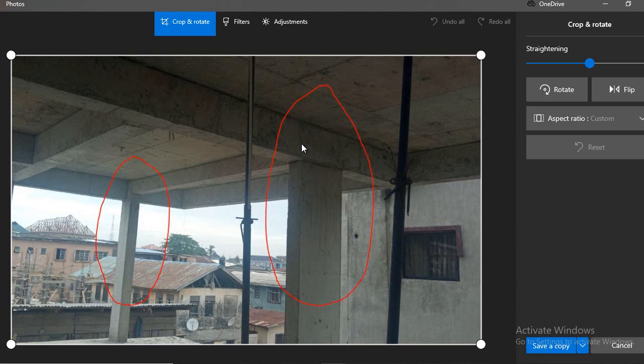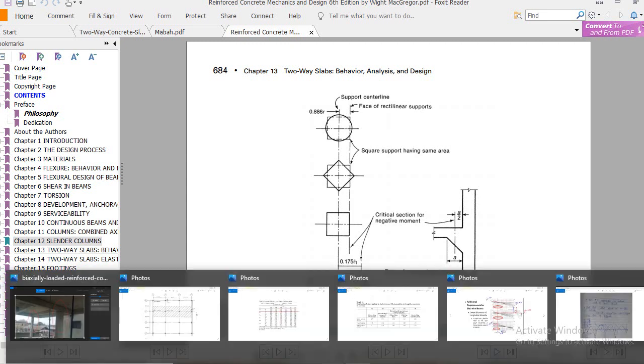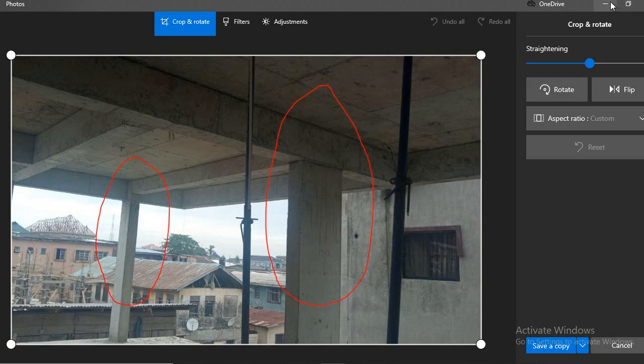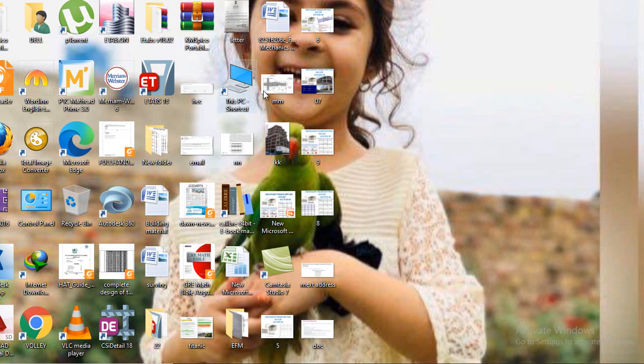There is some limitation of the ACI code which is explained right here. For example, if you have a shear wall, the C1 distance, or the side of that shear wall, should be greater than 0.35 L1 for a shear wall case, remember. And the face in case of a shear wall, I already shared one important diagram right here.